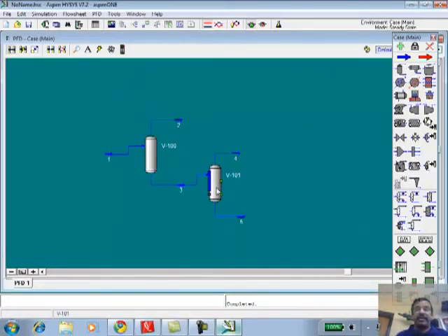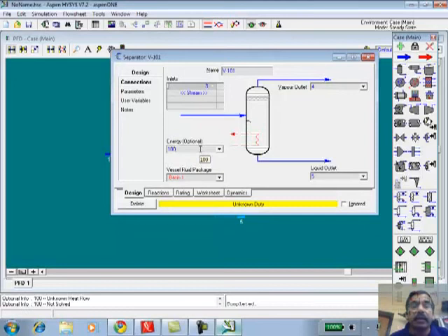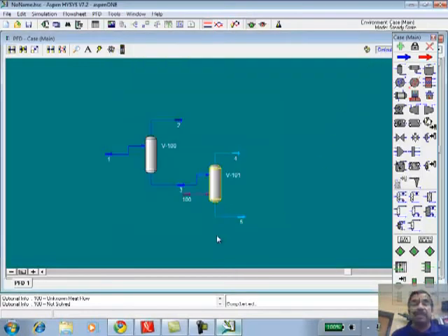For example, if I just say I'm putting 100. Oh, not there. Oops. Here. 100. What does that 100 mean? Is there a unit? This is just a stream. What it does is it adds an energy stream, because I forgot to add an energy stream. So it will add an energy stream and it will label it as 100.